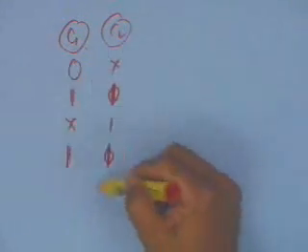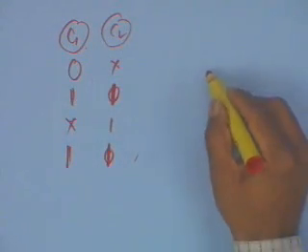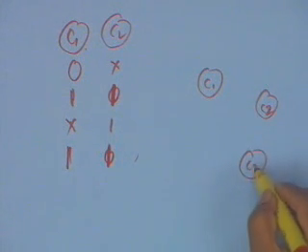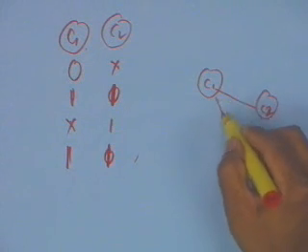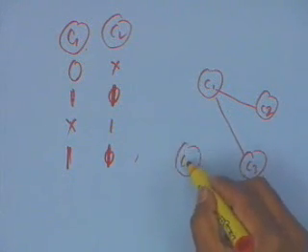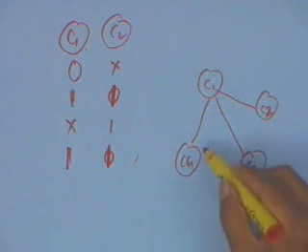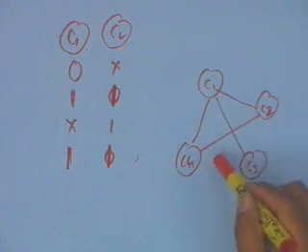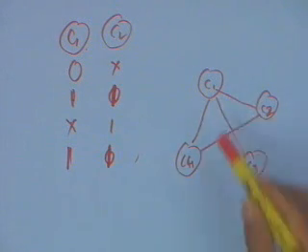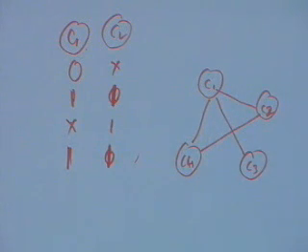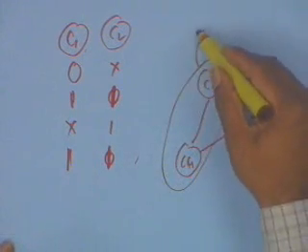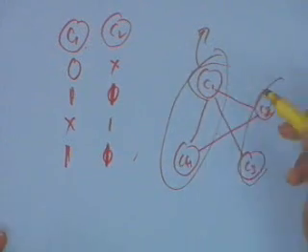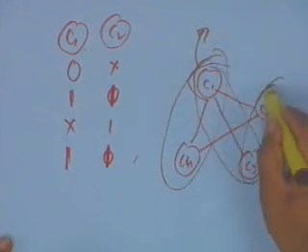And this can be done exactly in the same manner as what we had applied before. So if we make again another compatibility graph with columns and draw which are the columns which are compatible, then I can again generate a set of cliques on this. So in this case, let us say I can say that C1 and C4 are compatible and they can merge into one column, and C2 and, C1 and C3 and C2 and C4.